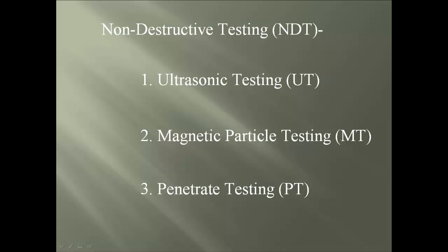And lastly, we cover the penetrant testing method, or PT as it's also known. This method also reveals surface defects by applying a liquid penetrant to a clean surface of the subject, and after a prescribed time called dwell time, a liquid developer is applied which draws the penetrant from the defect out for visual interpretation.